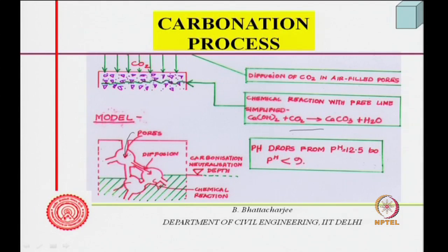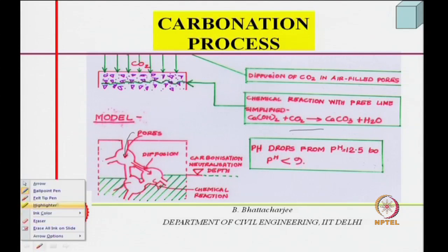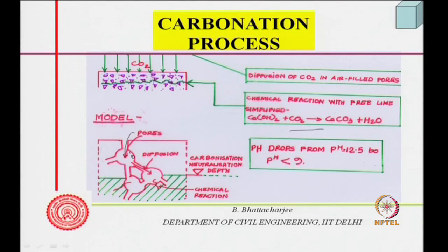and as it penetrates, it must be a moist pore, there must be moisture here. In the absence of moisture, the reaction will not proceed, because it occurs in the solution phase, and carbonic acid will not form. So, carbon dioxide plus water is necessary, and therefore, water has to be there. So, it comes through the pores, water has to be there, and as all alkaline material up to this zone is finished, we call it the carbonation,